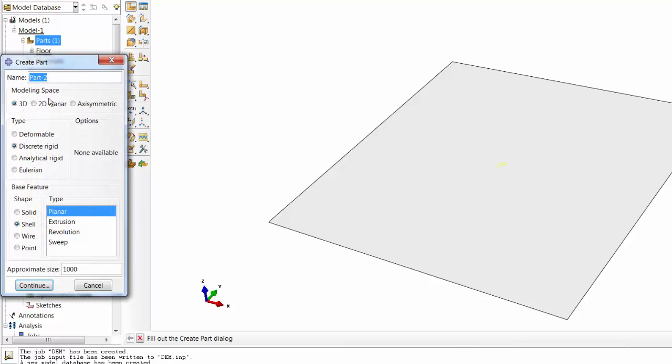Now we'll create a particle. So particle will be solid. We are going to have a circular 50 millimeter and then 100 millimeter in length. So we'll say solid, we are going to extrude it. So part will be particles. Now for particles, we have to just give a name, particle. We'll make a solid mesh, will not assign any material property or section property. We'll convert these solid elements into the particle, and then we'll define a section property for this.